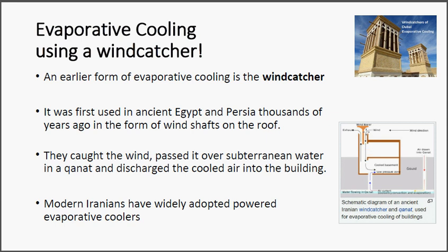The windcatcher sucks air out of the building, and the air is forced through a plane of water. So you've got a water channel, maybe a well or something like that, where you've got some groundwater. So the air moves across the water, goes into the living quarters, and then is moved out of the building. And so you're naturally sucking warm air out of the building, and you're sucking cold air, which is being cooled down with water, through the building. So that's how the windcatcher works.